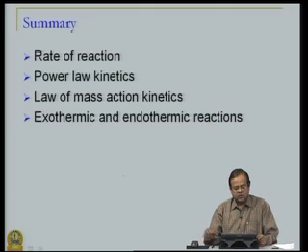So, to summarize, we saw how we define the rate of reaction. For a closed isothermal constant pressure system, we define the rate of reaction as the rate of change of extent of reaction normalized by the volume of the reacting mixture if it is a homogeneous reaction. If it is a heterogeneous reaction, we have several choices, such as for catalytic reactions we do it by normalizing with respect to the weight of the catalyst.